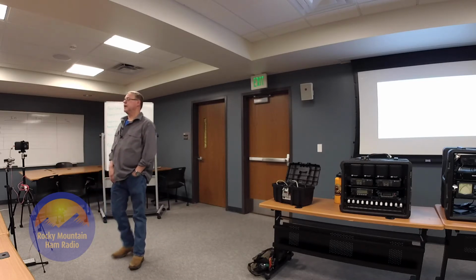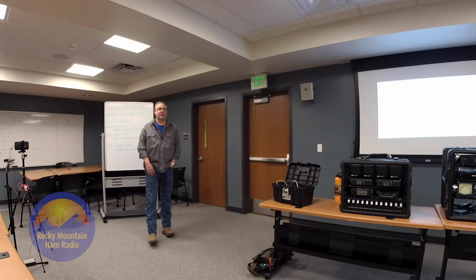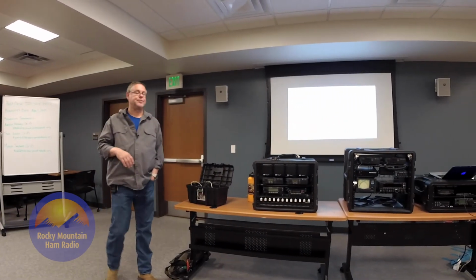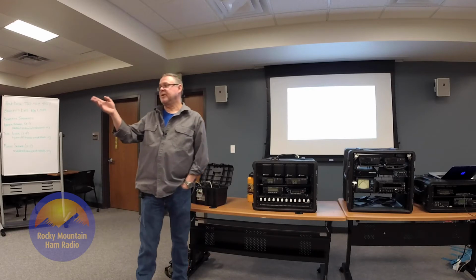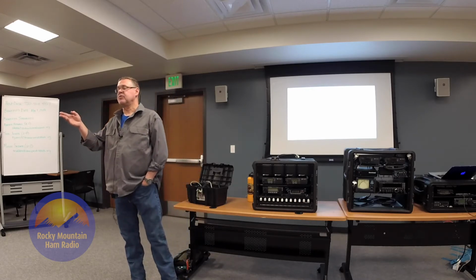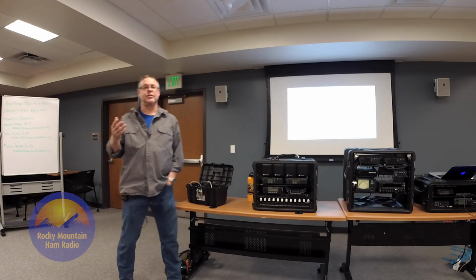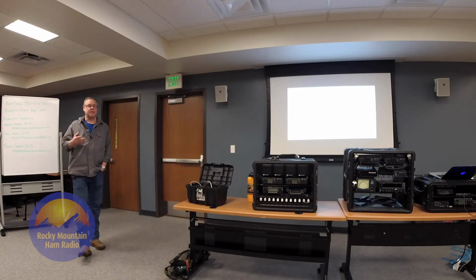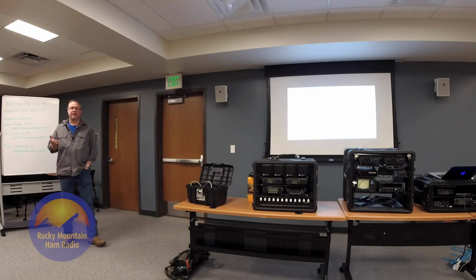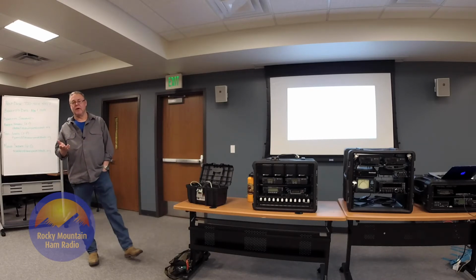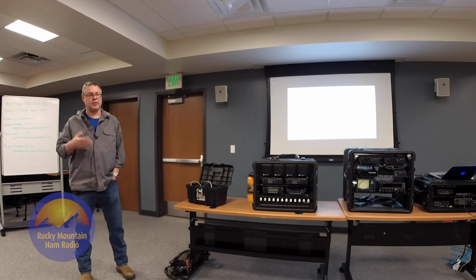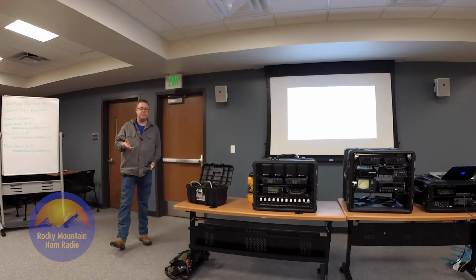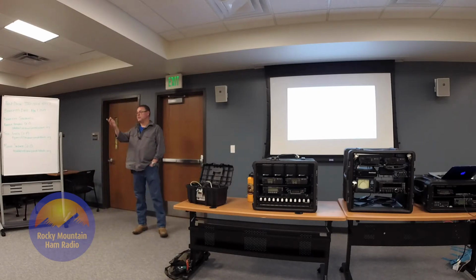That's a good point to bring up. If you go to Harbor Freight or Home Depot and you buy one of these generators, exactly what you're saying is going to happen. Those things aren't sine wave generators. They're not inverter-based generators generally. They're armature-based, magnetic-based generator systems, because they're cheap to build. And they're electrically noisy, just like you said.